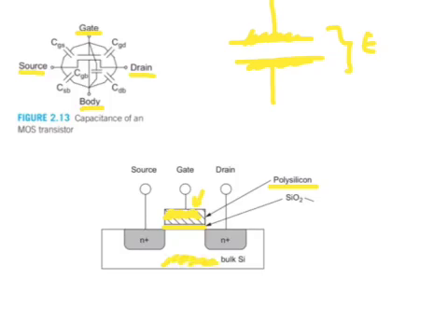Now, transistors today also have very small dimensions. The length of this channel is on the order of 10 nanometers. So this close proximity also gives rise to capacitance between free carriers in the source end region and the gate, and free carriers in the drain end region and the gate.